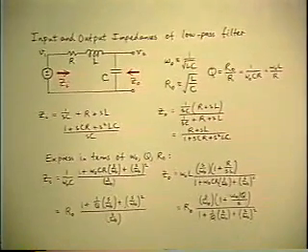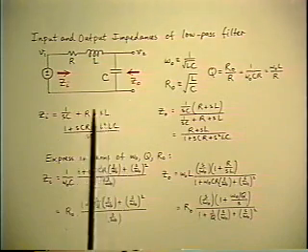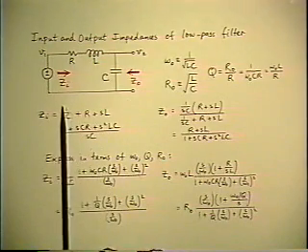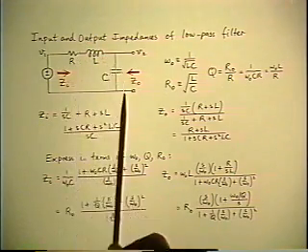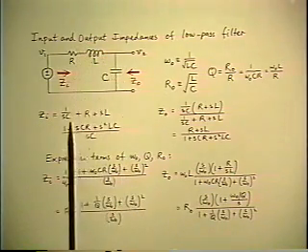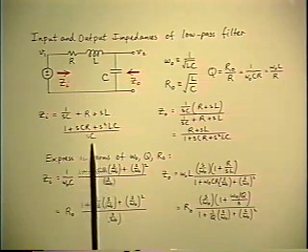Well, we talked about the voltage transfer function of the RLC low-pass filter. Now we'll go on to talk about the input and output impedances, which are usually important parts of the specifications to do with the filter. What you see here is the same circuit we're talking about, and we want to calculate input and output impedance. So the input impedance is just the sum of the three reactances in series. So in terms of the original circuit elements, this is what you get.